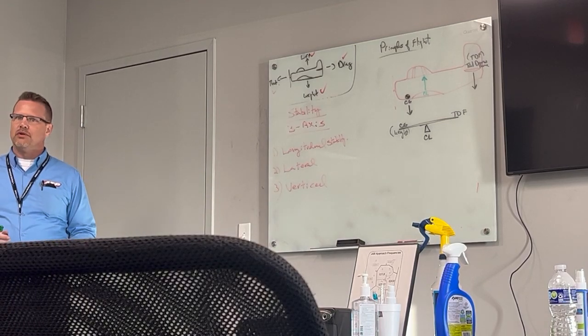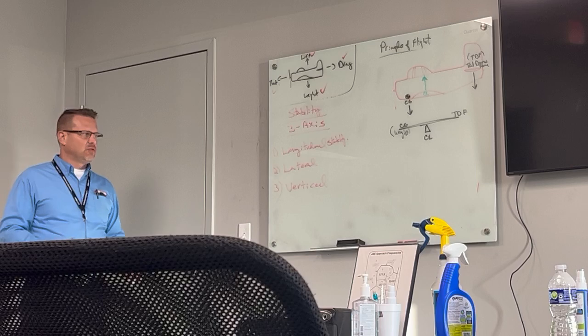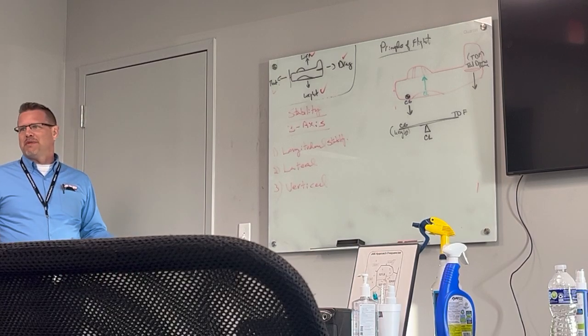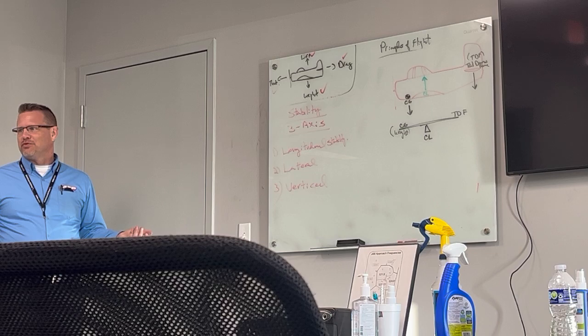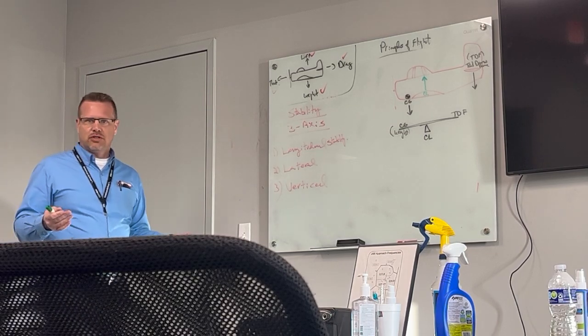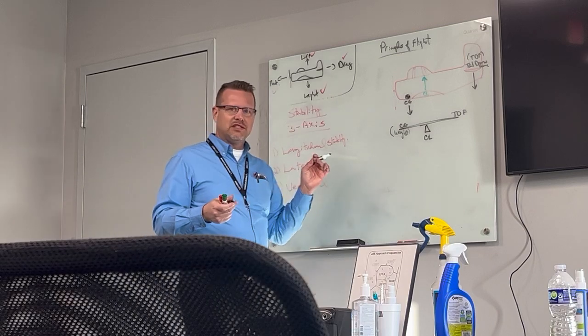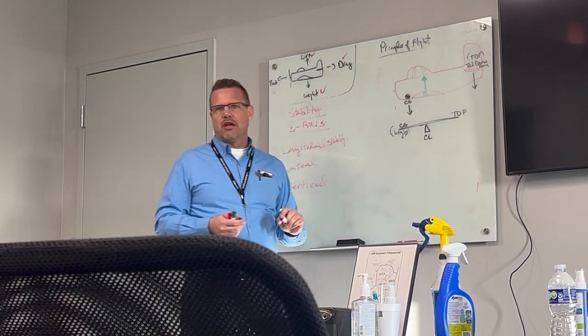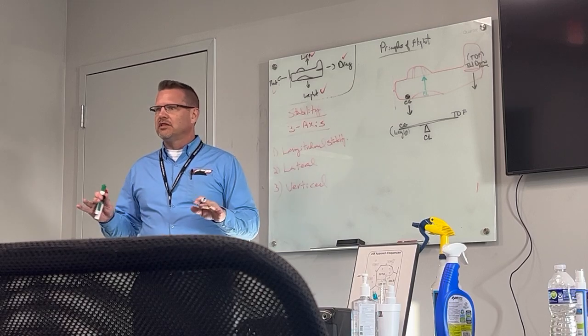Decrease fuel, decrease weight. But in any five-minute span of time, how much fuel do we eat? How much does the weight vary? Not much. So over any one instance in time, our center of gravity and our weight are relatively fixed.